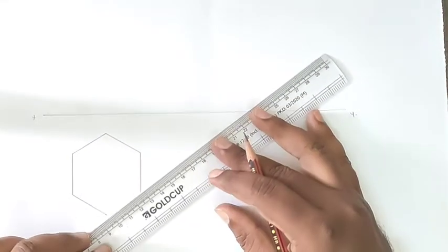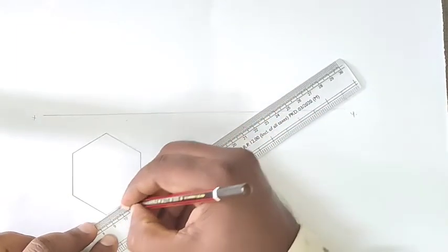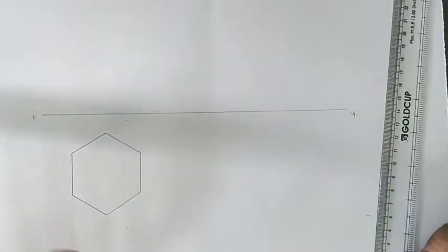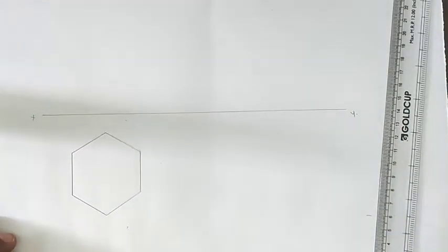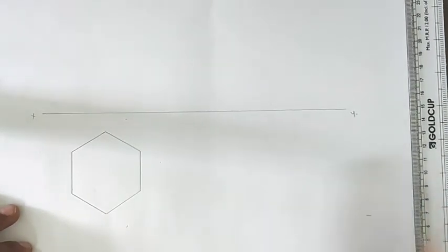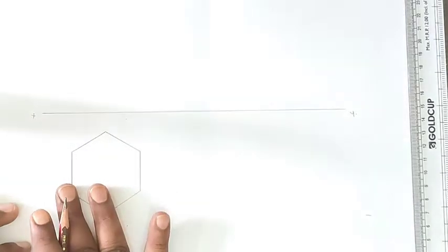So this is the top view of our diagram. When the triangle face is on the HP, on the ground, as given in the problem, the assumption is very important. We can assume the base is on the HP. When the base is on the HP, the axis looks perpendicular to the HP, so we will draw the top view as the base. In that case, we draw the top view with an edge of the base perpendicular to the VP.